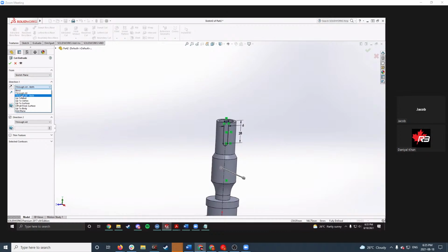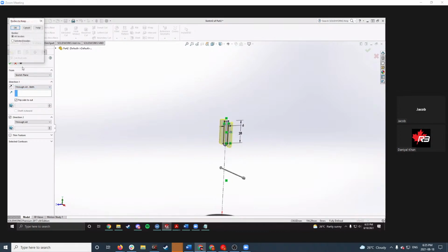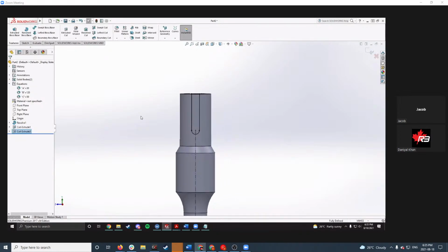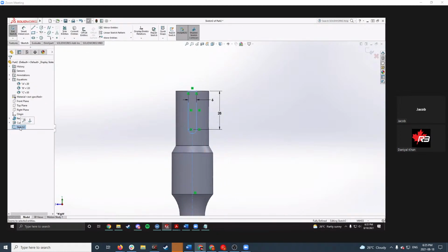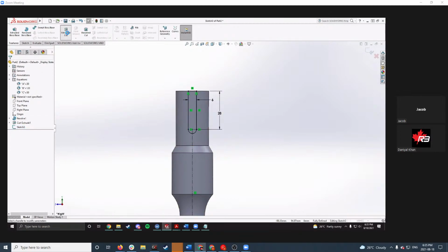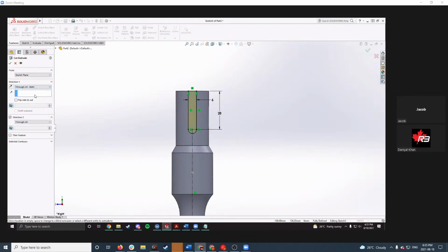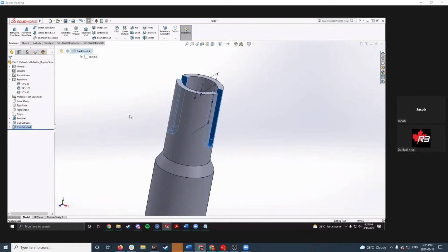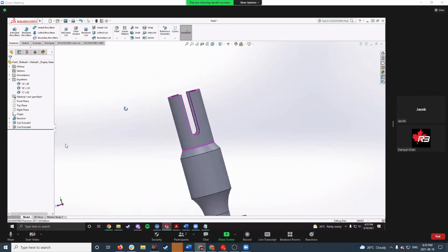Through all both from sketch plane, click OK. All bodies. Oh, sorry. I think I had something else selected. Through all both. Yeah, okay. I think I must have had an extrude selected or something. So we have our cut extrude now. We have our slot.